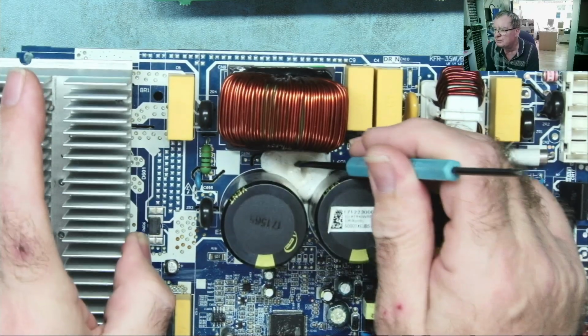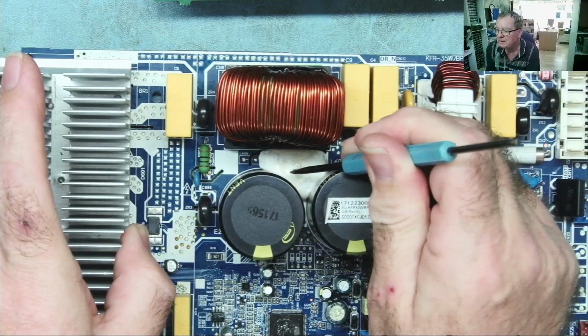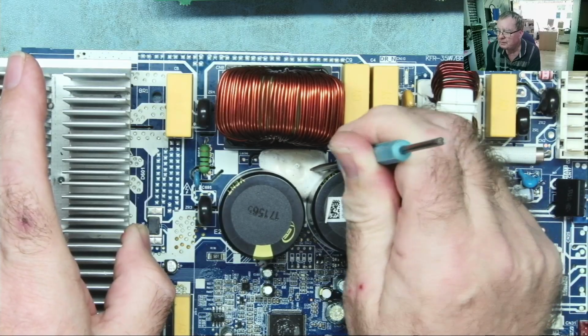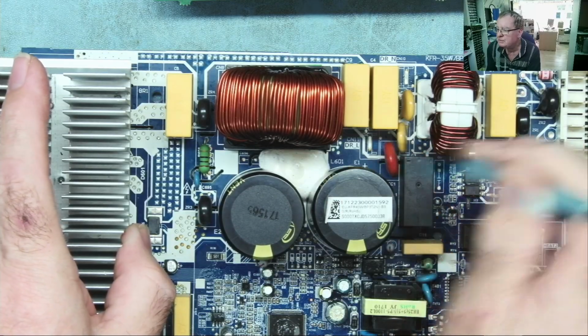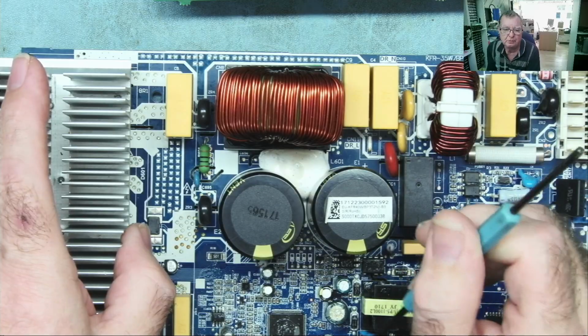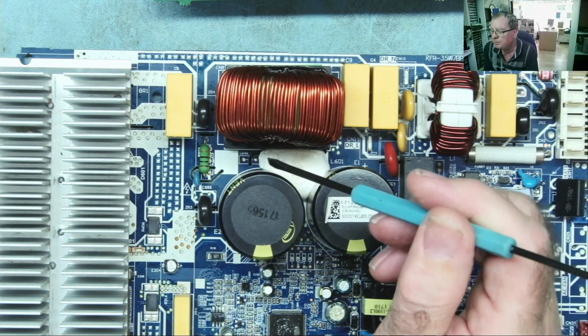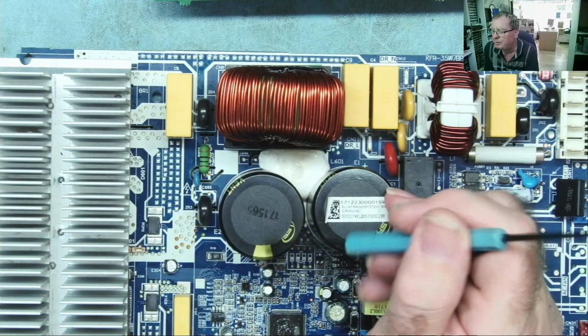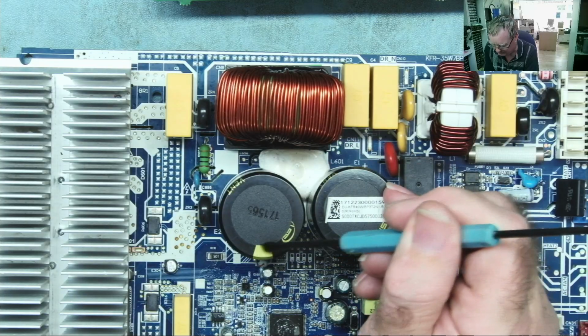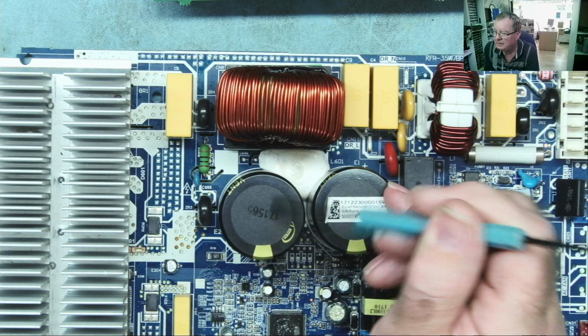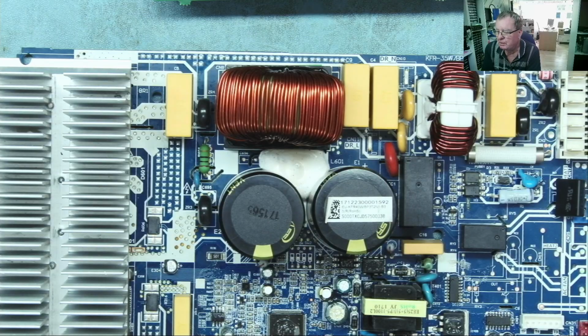There's this white stuff. This is like a silicone type rubbery stuff. In my experience, this doesn't fail and doesn't cause any problems. The one that causes the problem is more like this yellowish colour, or at least it is when it starts off, and especially due to age and heat it turns brown and then eventually to dark brown and then to black.